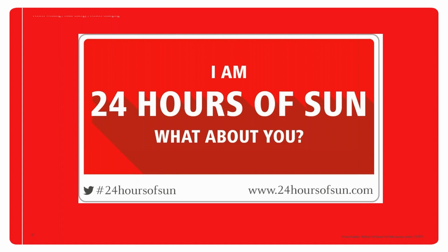There is a question from George. In the Volt-Watt settings, where does the enable limit voltage come from? That enable limit voltage is the V3 value specified in the table. So you will see that in the Volt-Watt response mode table, there is a V3 value, and that's the enable limit that we need to enter on the display screen of the inverter. When you go to the volt-watt power reduction, go down to enable limit, and that's the V3 value specified in the table.